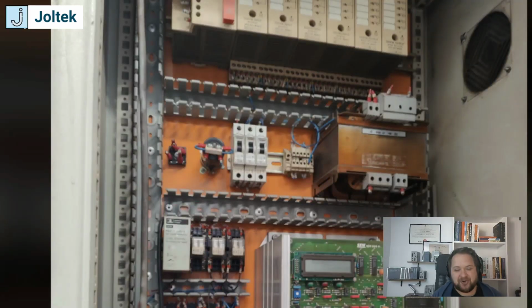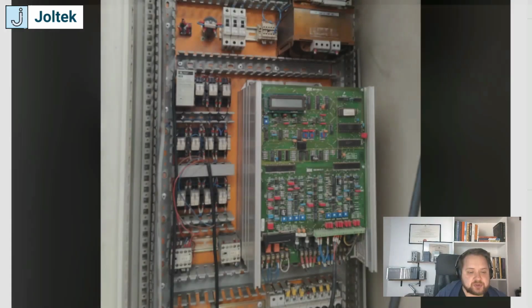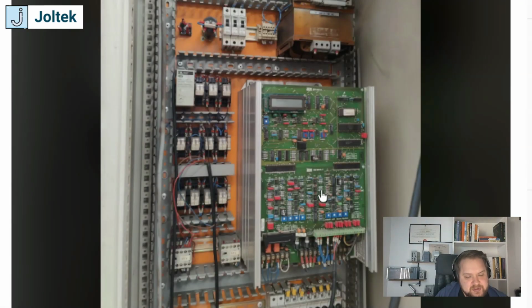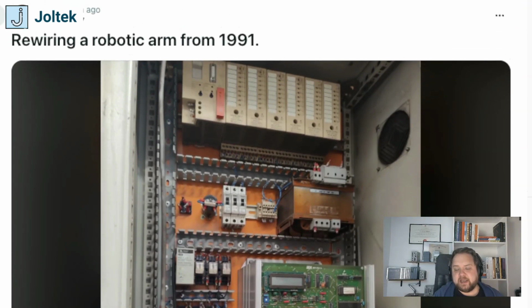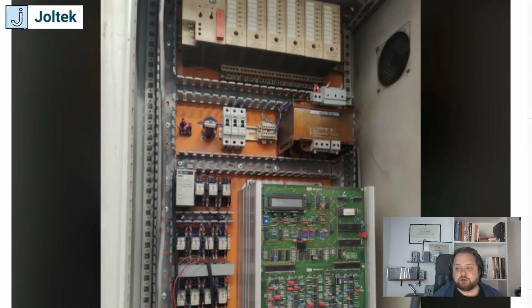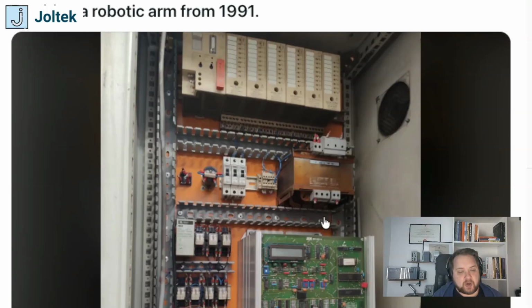So I would start by collecting the part numbers of the largest components. In this case, it's going to be your PLC, it's going to be your VFD, and whatever is driving the robot, of course, and the robot itself, and some of the peripherals on that robot. So he mentioned it's a 3-axis robot, so I would start there. I would then look for manuals as well as OEMs, so the manufacturers of that equipment, and I would start figuring out, since he's already looking into the migration, what does that look like? Is it easy enough to migrate, or is it going to require a lot of effort?